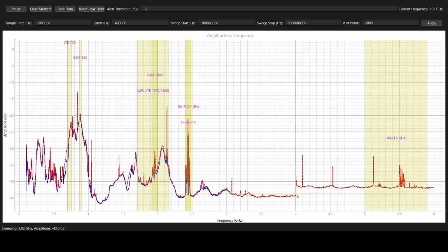Meaning that, for instance, we don't have an oscillator that is able to generate the entire range from 100 megahertz all the way to 6 gigahertz. Usually, this is done by 2 or 3 different oscillators that are switched based on the RXLO that we said. Also, we may have dividers after the oscillator to generate this wide range.